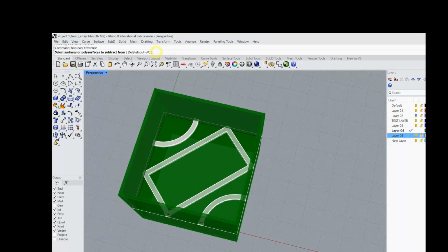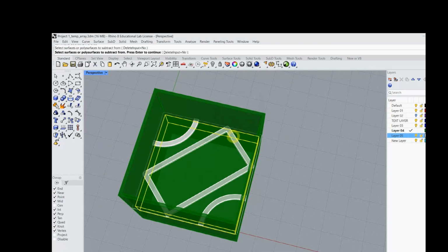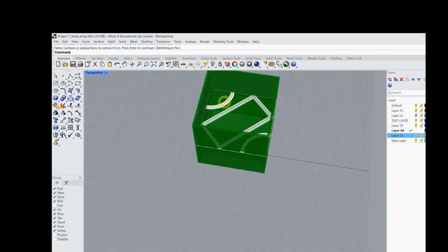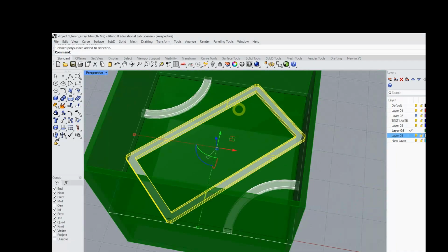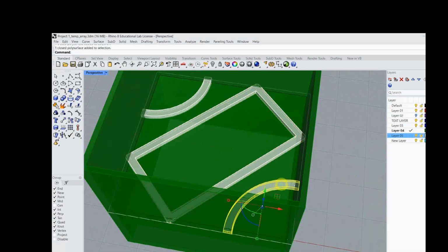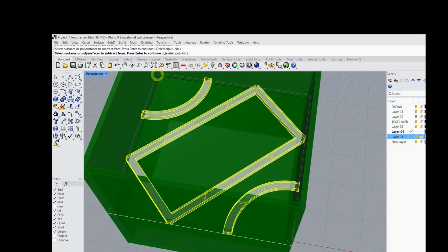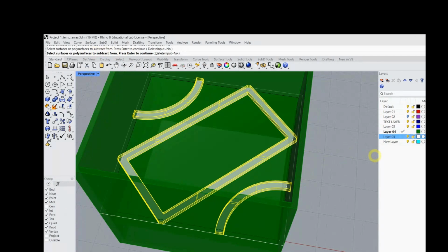so I want to subtract from these, just hit escape if you're having trouble selecting. So right now I do have 2 poly surfaces there. That's just one. That's just one. So I'll do my Boolean difference. Use shift to select these. So I'm subtracting from those.